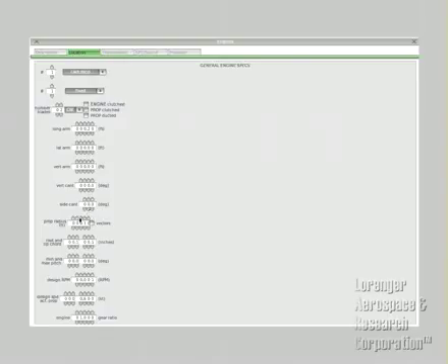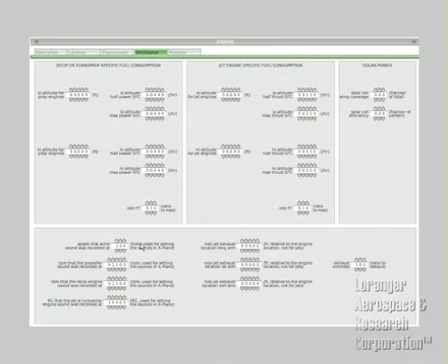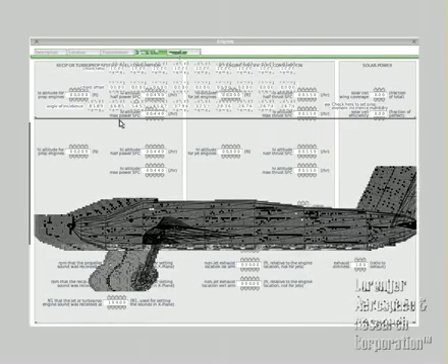And in your engine, you're going to change this many, many times. The propeller here, this is a quick rubbish scenario. You never want to do this, and your design RPM is just ridiculous at 4,000. It shouldn't be that. It should be 2,700 RPM, typically, especially for propeller-driven aircraft. That's generally the ballpark, at least from my experience. And in here, there are a lot of things you can fiddle with, but you can get around to that later.